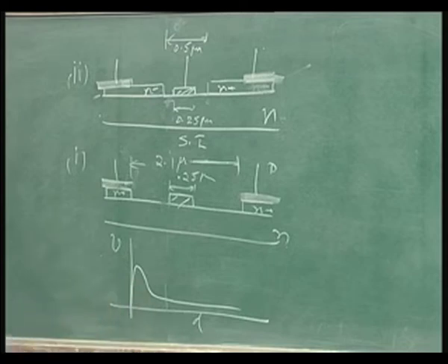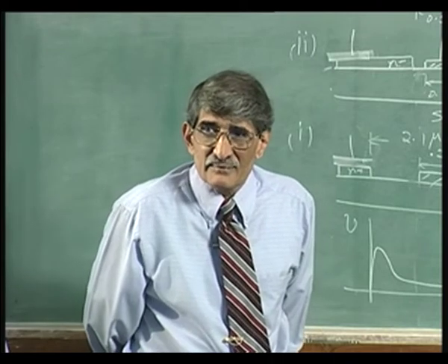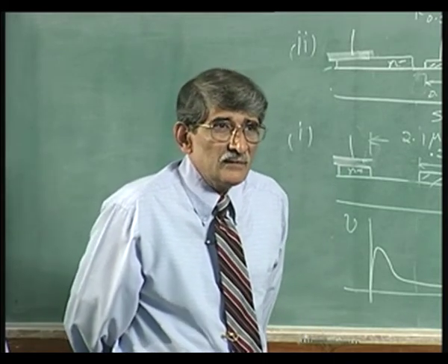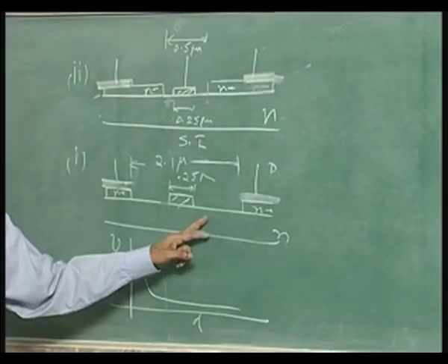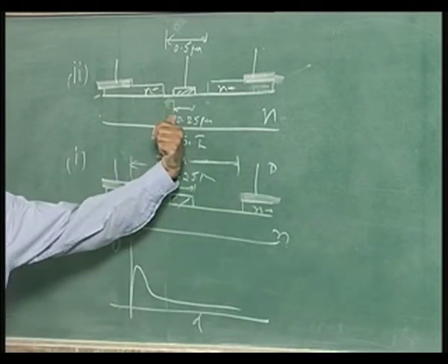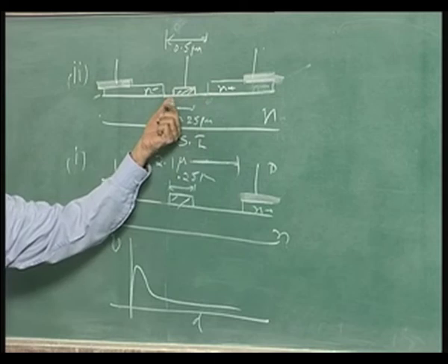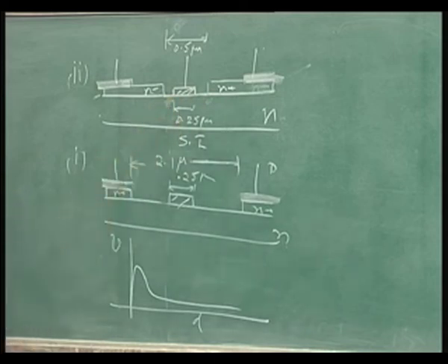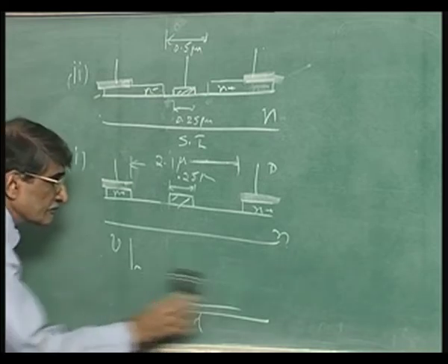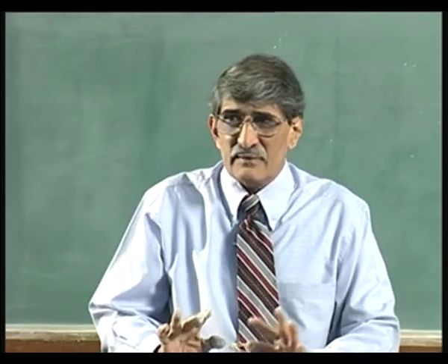Now, what do we conclude from here? What we conclude is, if I have to make a device with gallium arsenide, short channel device, you can't afford to make it like this, absolutely no use, because the GM is small, comparable to silicon. You have to have a device like this. Best device that you can get would be this merging with that. Self-aligned structures, let us take a look at that. There are several other curves which are there in my slide, but I will not show it right now. Since we are on this topic, let us get into this. Let us get back to other things afterwards.